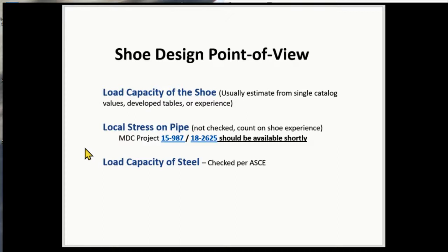In the few cases where high restraint loads, due mainly to thermal expansion, slip through the experience filter of the checker that we use now, problems can exist though. What we want to do is catch these problems before they impact the project or before they make it to the field. We would like to help the structural engineer or the support engineer check that he's gotten the support loads correct and that he's buying the right supports for each point in the piping system.